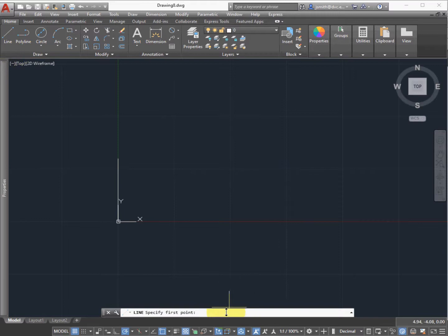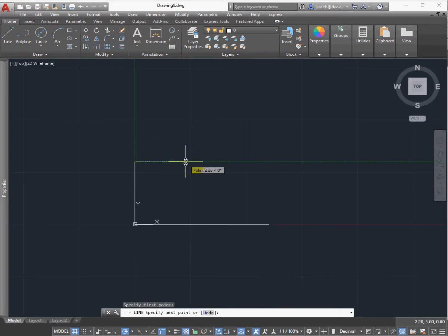All right, so then I'll take that line, and I'll start at 0, 0 again, and then type in 3, actually 6, push enter, and then I have half of it built here. My snap setting is already selected, so it's going to snap, and I'll move that out to the right. This time I'm actually going to go 2 inches because I'm following the Spencer design part, and I'm going to come down 0.5 inches. So I'm going to type that in and then push enter.